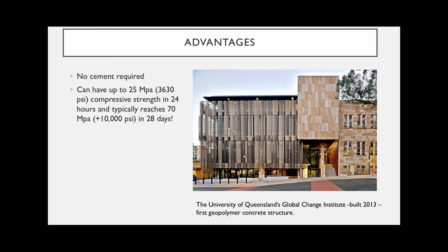So this stuff's strong. What's amazing though, and we have done this in the lab, is within 24 hours, you can get almost 4,000 psi in 24 hours. So if you need to do runway repair for an airport or freeway repair, think of the strength that you can get without anything special added to your mix. And you can make these even stronger if you need to. This is sort of your standard mix.